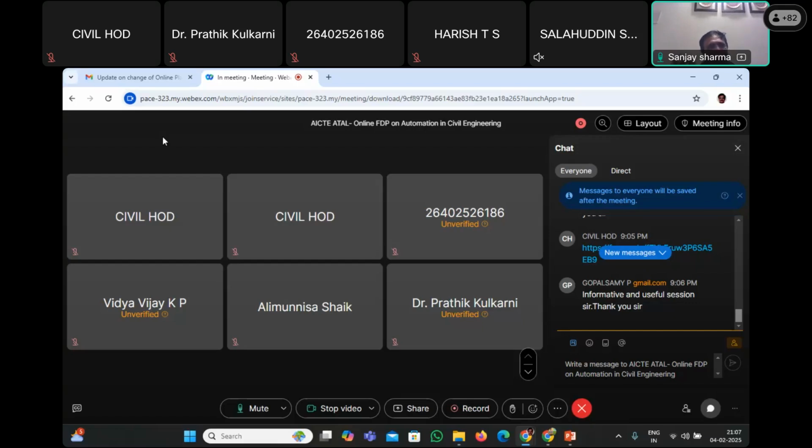But condition assessment means deterioration has taken place, you want to know the present strength, and you want to know the corrosion. So basically, for strength, mostly we are using the rebound hammer and UPV, both tests we do.